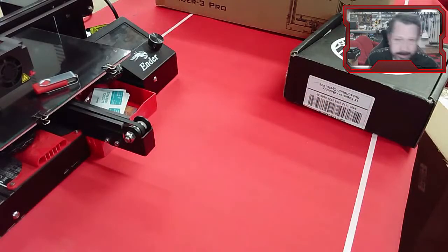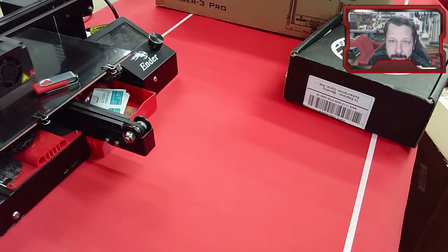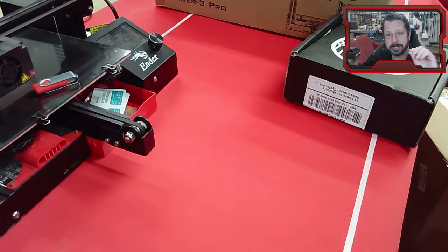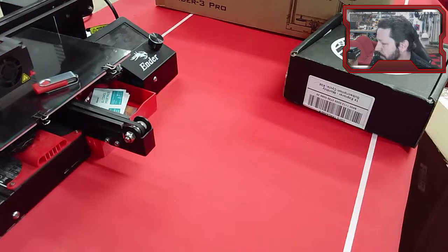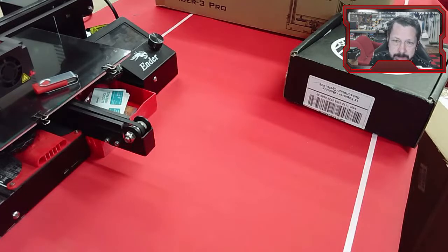But expect to pay about $20 for a kilogram of plain PLA. You can get it a lot cheaper. If you go very cheap, unless it's just like a clearance sale or something, then you might have trouble with it because it doesn't have quite the quality control, and it'll have thick spots and thin spots, and it'll just not print very well. Or it's blended with HIPS or some other material that's not just PLA, and it makes it very brittle and hard to print.